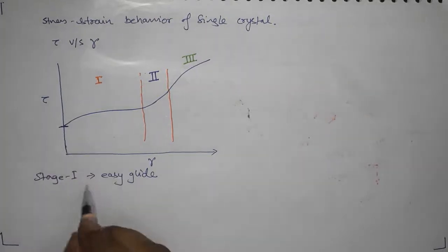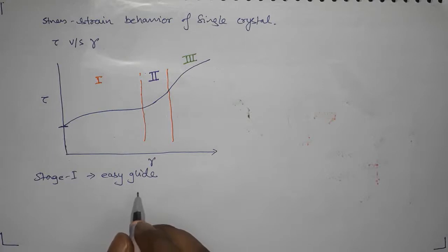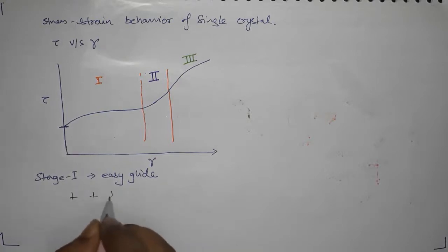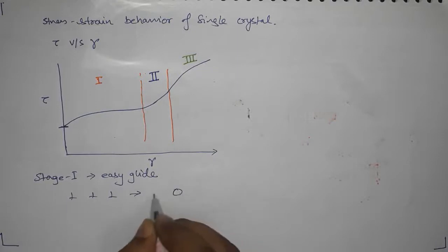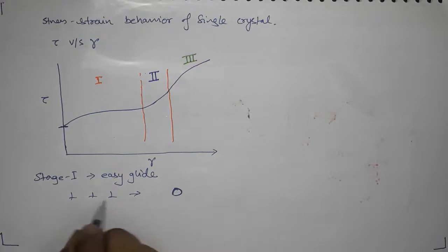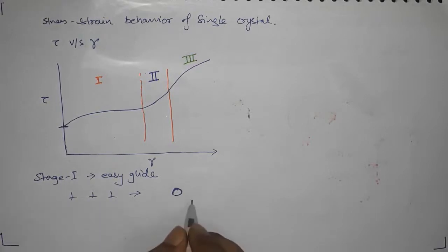Once they start moving, they are not going to intersect in the initial part with each other, depending upon the number of dislocations you have in the system. If you have already a very high number of dislocations in the system, they are going to interact with each other. But if you have a low number of dislocations in the system in the initial part, they are not going to interact with each other. They are going to flow, okay, and they're going to only stop at the barriers like precipitate or something, which is a longer distance barrier, okay.